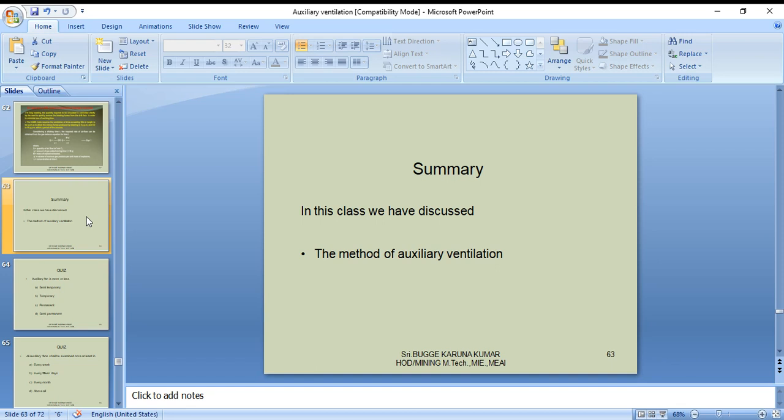I hope you understood the basic purpose of auxiliary ventilation, the methods for ducting, the types of ducts, installation of ducting, forced and exhausting overlapping mechanisms, and standardization without affecting the main fan system.